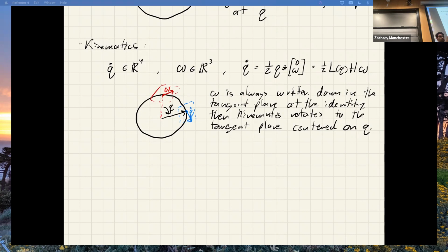Make sense? So thinking about it as Euler angles gives you all these wrong notions in your head. Angular velocity is a good idea. Omega works. That's a real physical thing. You measure it with your gyro on your IMU. That's what comes out of a gyro strapped down to your system, right? That's totally good. And what that is, again, is the axis of rotation scaled by the angular rate. That's a very well-defined thing, and that is a vector. That does add like a vector, behave like a vector.